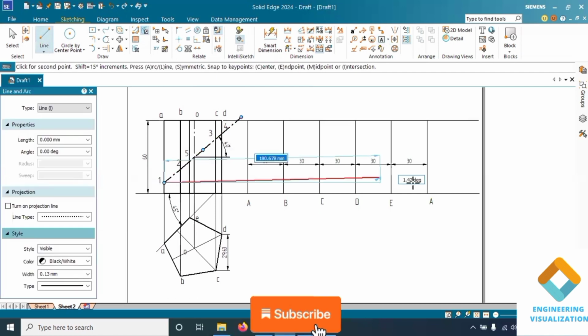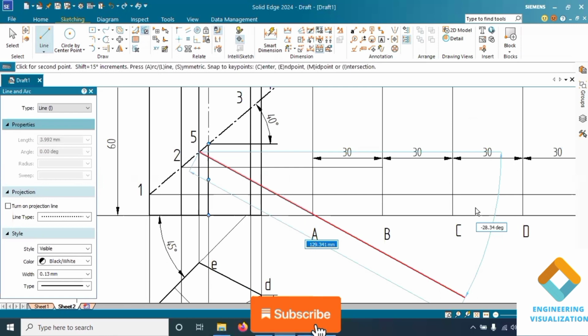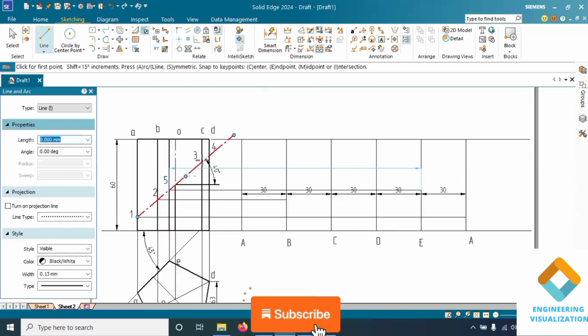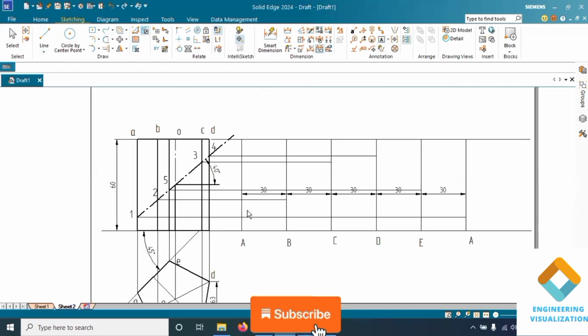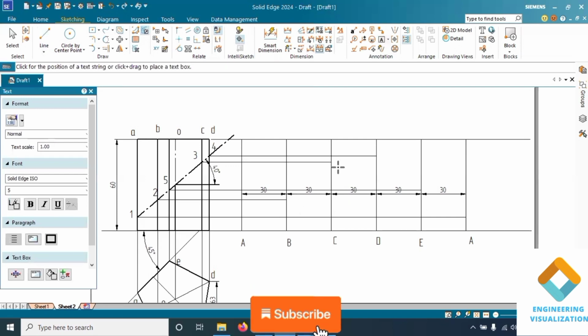Yes, the cut point of 1 should be on the vertical edge of A. That's why I'm extending it, so you can mention it now. Same, 2 is on the vertical edge of B, 5 should be on the vertical edge of E, and then 3 is on the vertical edge of C. 4 should be on the vertical edge of D. So now we need to write the cut point names: 1 on the vertical edge of A, 2 on B, 3 on C, 4 on D, and 5 on E. Now we need to connect all these points using straight lines.